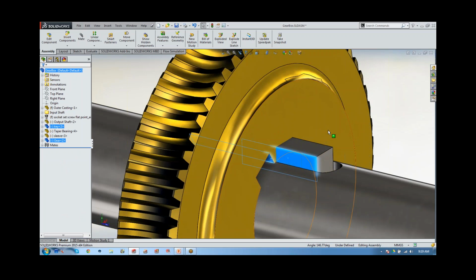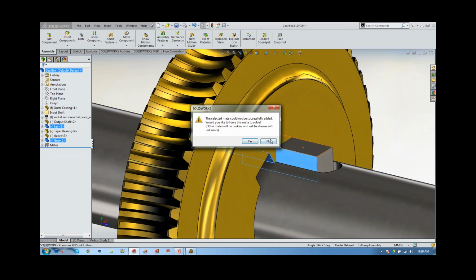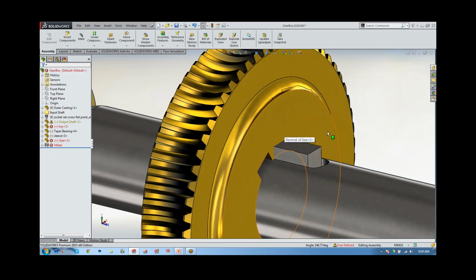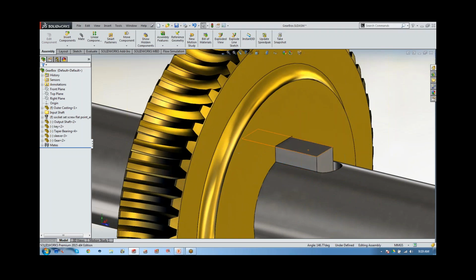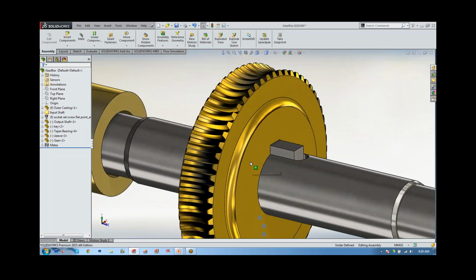If you move your cursor back over where that context toolbar was at, hit the control key on your keyboard. That'll bring that context toolbar right back, and then you can add the necessary relation. We'll go ahead and add a parallel relation there. Make sure things are good.